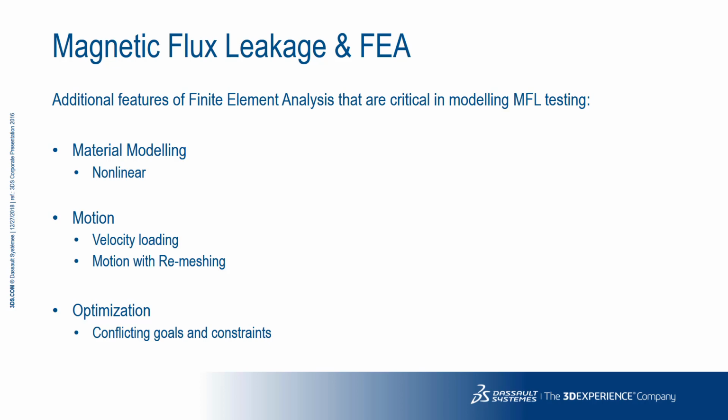Numerical approaches to this problem include 2 schemes. Firstly, it can be solved quasi-statically with an extra movement component added to the formulation. Or secondly, the relative movement of the probe and pipe can be analysed over several time steps with the problem automatically repositioning and remeshing as the solution progresses.